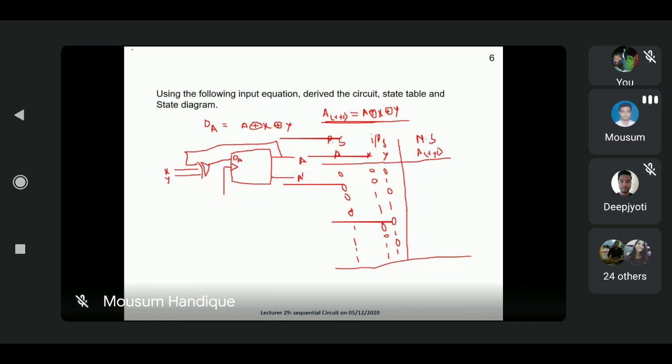See here, when we are using the state table or excitation table, we cannot use it here. It is not possible. The state table also we cannot use, because when you are getting any particular flip flop value, suppose we know the value of DA, then whatever value DA is coming, that same value occurs in the next state. You can check the state table of the D flip flop. But unfortunately, here DA is missing. So what Udesh is saying is correct.